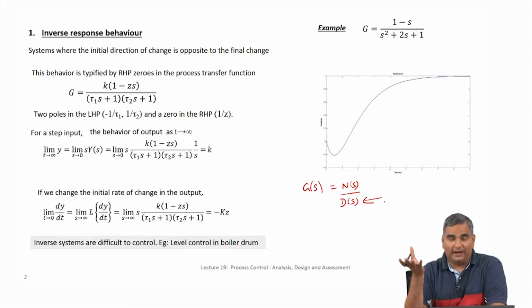And purely from an analysis viewpoint, if I wanted to do an inverse Laplace, I really needed to know only the denominator polynomial root resolve form, and then each term can be individually inverted, right. So, there again the numerator polynomial plays a role, but not explicitly, it is just that the coefficients are computed based on the numerator polynomial. And when we come to stability again, if you are really looking at the denominator polynomial, then again you are not really paying much attention to the numerator polynomial.